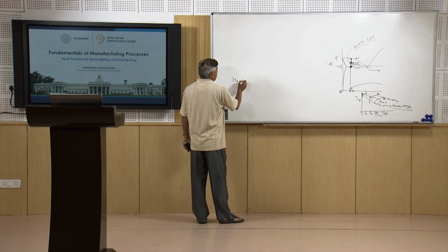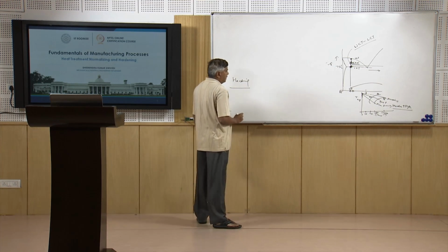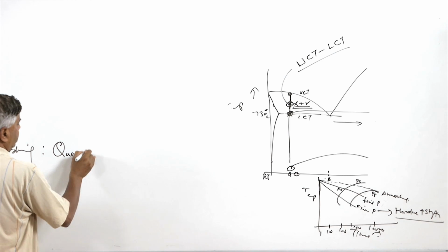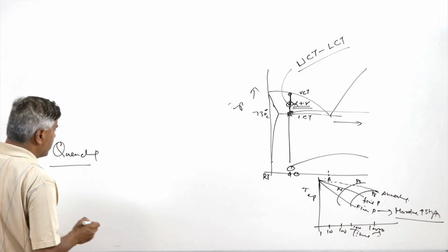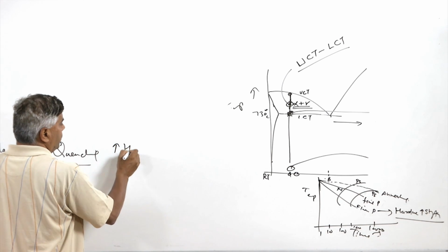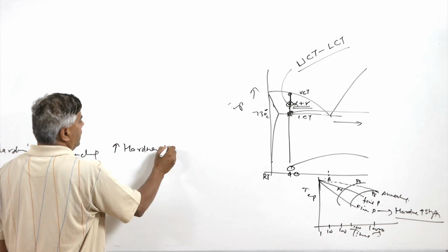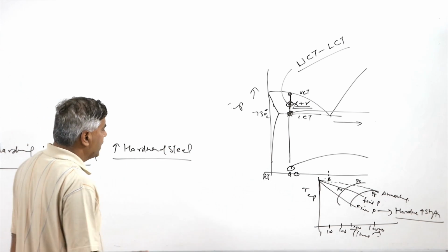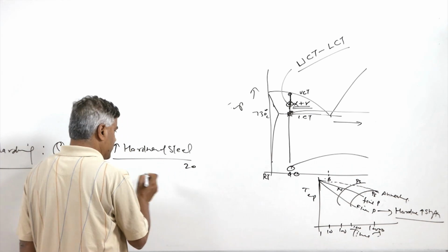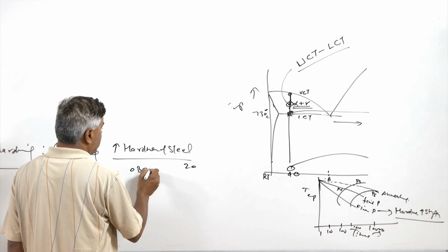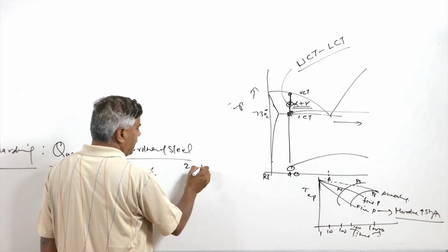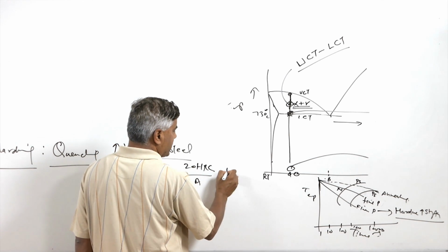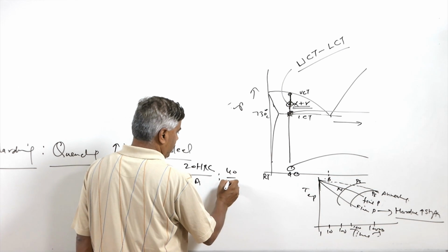Coming to the hardening treatment. Hardening is also known as quenching heat treatment, and the purpose of the hardening treatment is basically to increase the hardness of the steel component. Normally, in annealed condition or in normalized condition, steel of composition say 0.8% carbon content may offer a hardness of 20 HRC in annealed condition. In normalized condition it may be 40 HRC.